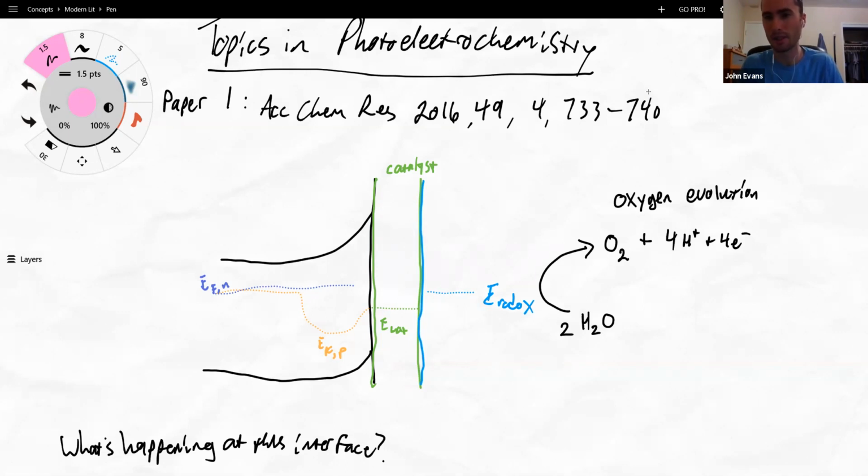And so this is not strictly the Fermi level. This is sort of, I think, the surface potential of our system. So it's a little bit different than what we normally look at, but everything here you should be able to understand based on what we've looked at so far. So we have our semiconductor. We have a Fermi level here. This is the Fermi level of our electrons. And then we have this quasi-Fermi level for the holes, which sort of dips down like this.